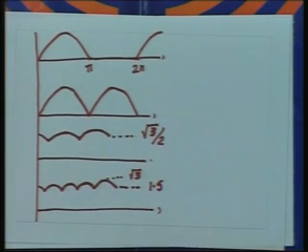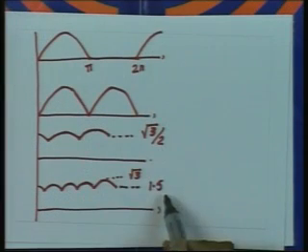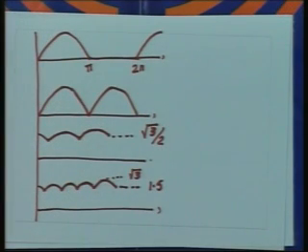What happens in the 6-pulse? We discussed yesterday, for alpha equal to 0, which is equivalent to an uncontrolled bridge, that this voltage changes from 1.5 per unit to root 3, that is approximately 1.7. So in a 6-pulse converter with alpha equal to 0, the variation in the output voltage is 1.5 to 1.7. That is approximately constant for an engineer. I can say that the output voltage remains approximately constant. I may not require any filtering.